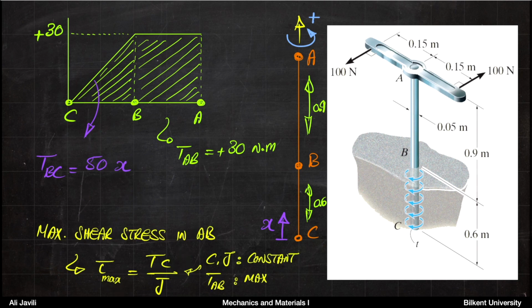Okay, so now you have almost everything you need. You have the torque distribution, the internal torque distribution. And I think, again, this is possibly the most important part of this question. Once you have that internal torque distribution, you can integrate it from, let's say, x0 to L to calculate the angle of twist or anything else that you want.